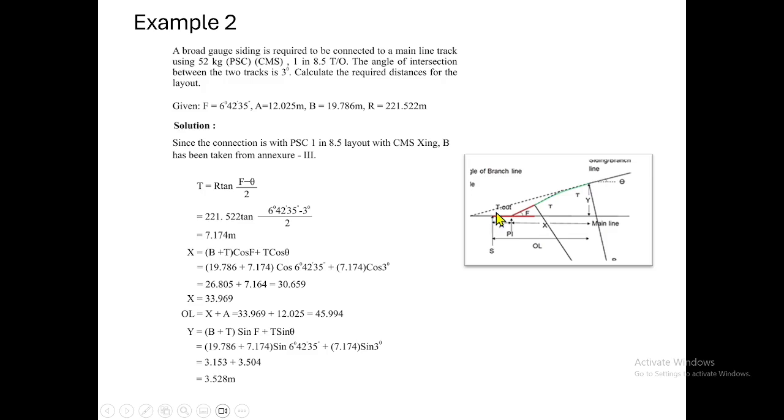So this will be in a reverse curve form. Being a small curve, now you can use the offset method or the successive bisection of arcs method. Or, off late, we have total stations. Using that, we will be able to fix the curvature. So this is about the design of this divergent track when the siding track intersects with the main line and the angle of inclination is lesser than the angle of crossing. This is something about it.